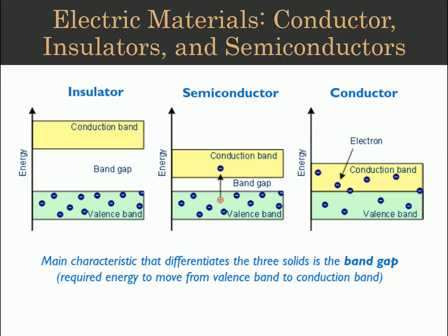So if we talk about conductors, we can categorize them into two different layers, where the first layer is called the valence band, where the charges reside, and if we apply an external force, that external force can be a potential, a light source like a photon, or it can be heat. It basically excites these charges and they jump from their valence shell to what is known as a conduction band, and here these electrons become free and then they can conduct or form different bondings.